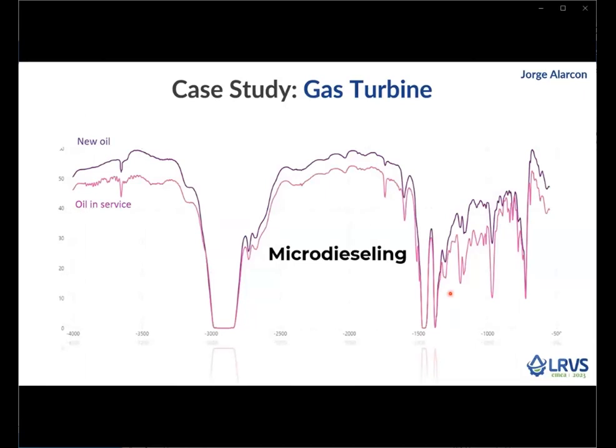When we were investigating this situation, we found that the problem was the missing quality control in the bleed and feed oil that was used. In this case, around 86% of the anti-foam capacity of the oil was lost. It is not an additive; the property of the base oil was missing due to situations like poor storage or stuff like that, right?